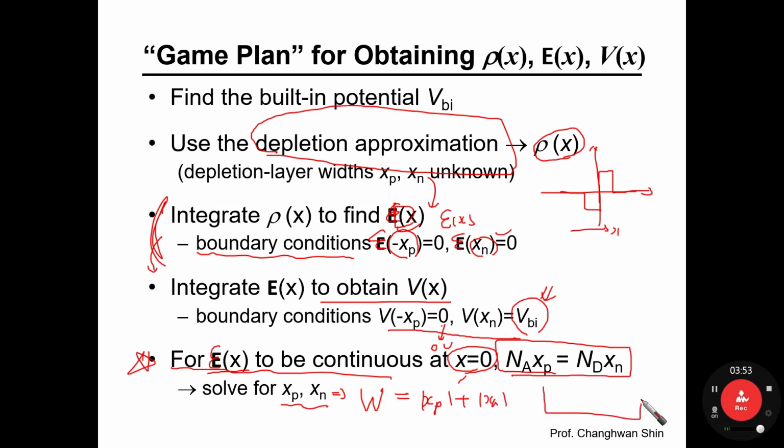Okay, so for a given PN junction diode, the depletion layer should be formed in between. Then we can claim that, say, a 100 nanometer depletion layer has been formed. So why is it important? Going back to the MOSFET, in the cross-sectional view of the MOSFET, this is a p-type substrate, n plus source and n plus drain, and that is another PN diode, right?